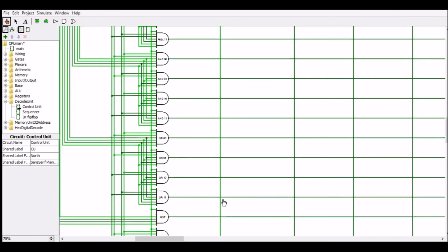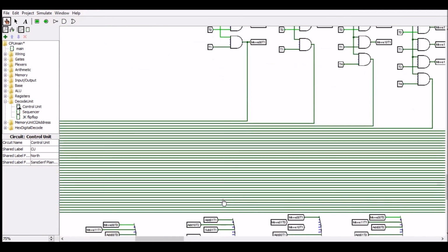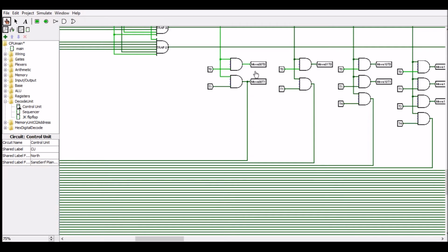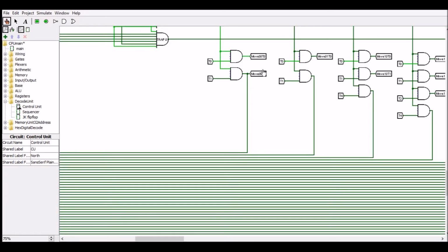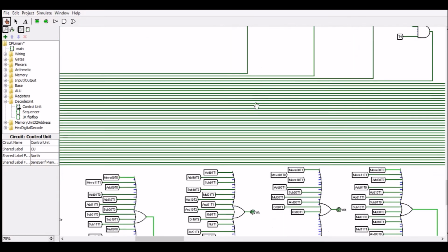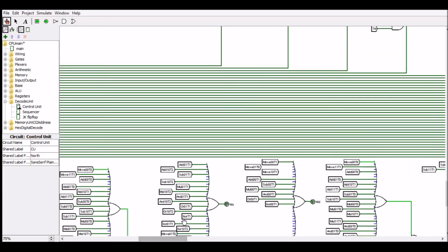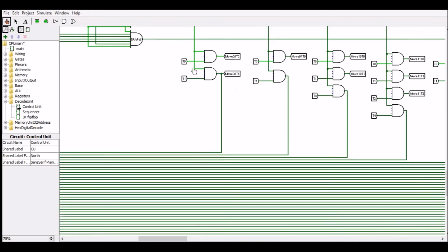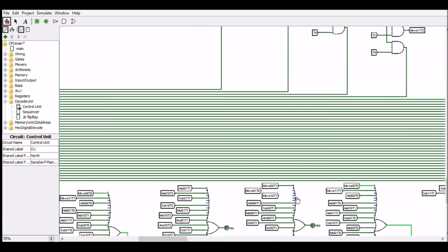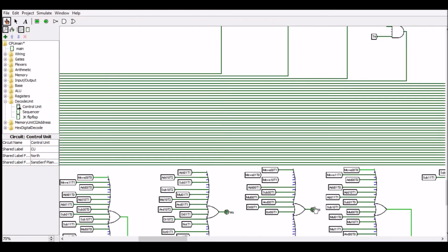So we'll go down, and at time T0, the move 0,0 T0 instruction part will be executed, which will set some of the timing signals, like clock X here, and we'll set the appropriate ones in order to implement that part of the instruction. And then at T1, the next part will be implemented, such as there's a one here for writing to the destination register.